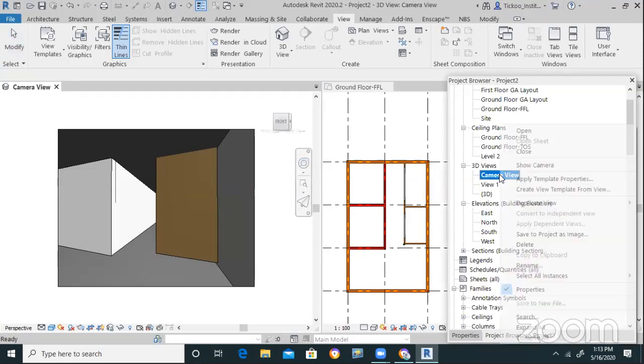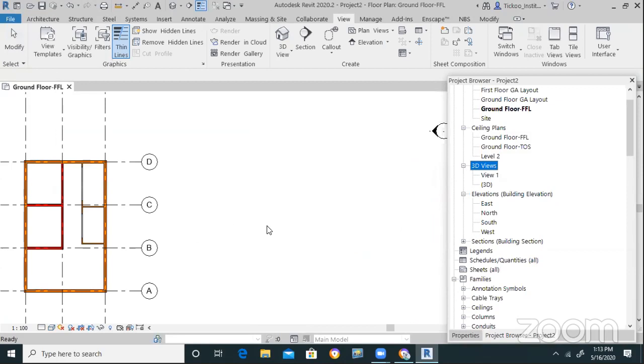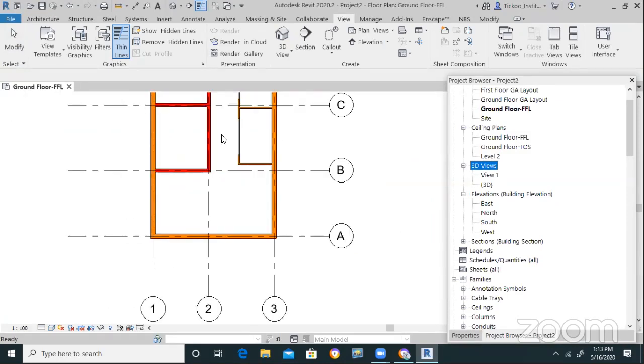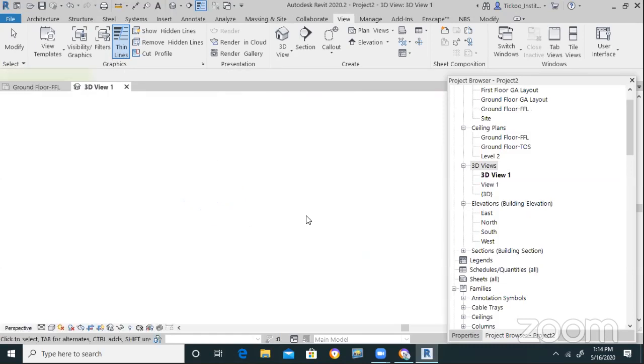So let me delete this camera and let me position a better camera. Let's say I want to see the camera view from this particular part, and I want to develop this interior of this particular part. So I have this view, and 3D view. I want to go with the camera view. So I have this angle and the height 1750 from the ground floor FFL. So let me have this, let's say this is the view that I want to see.